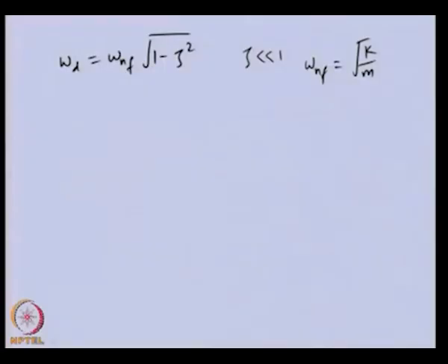So, energy is also growing, so amplitude will also grow, because energy is something like the square of the amplitude, like in the case of strain energy. So, strain energy is the square of the displacement, or kinetic energy, that is the square of the velocity. For simple harmonic motion, we can write it again in the form of displacement. So, energies are nothing but something like the square of the amplitude of the vibration. So, we expect that if we want to plot the energy with respect to the amplitude, that will be parabolic in nature.